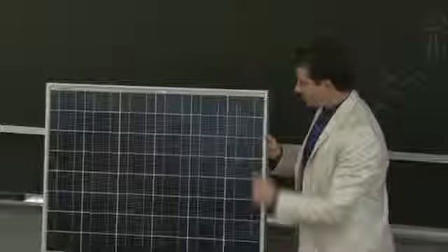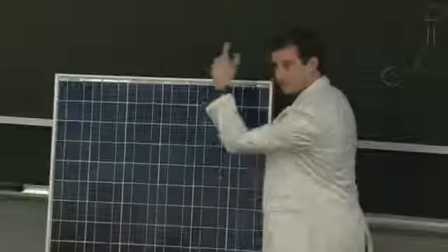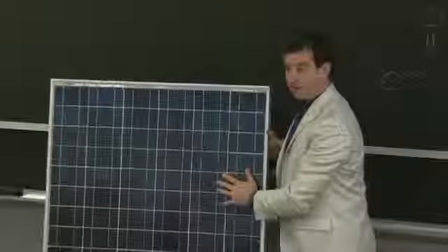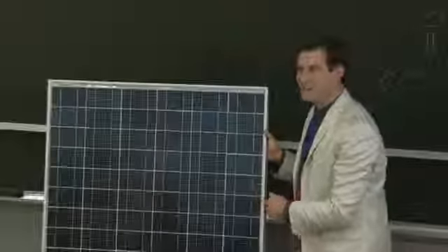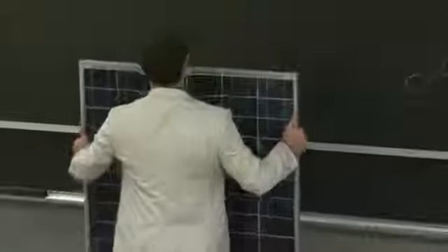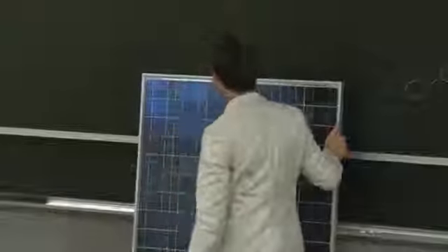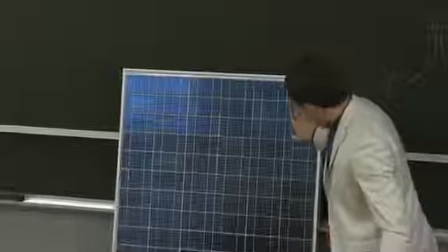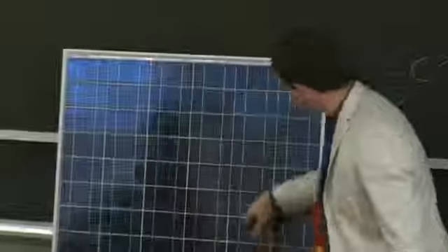Do I connect them all in series and make just one long, snaky electronic path? Do I connect them all in parallel? That would require a lot of wiring. Or do I do something in between? And if you were to come up close to here and inspect it, what you would see is that you have strings in parallel. So you have one going from here down and around. That's 1, 2, and 3, right? 3 of these strings, and those 3 strings are connected in parallel. And each string is comprised of several solar cells.